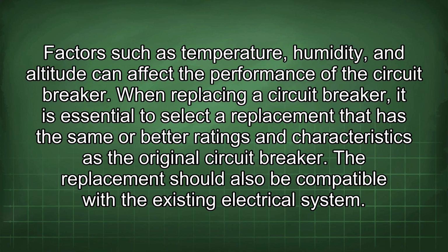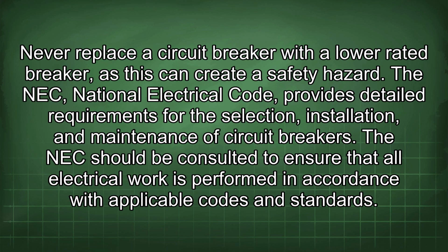When replacing a circuit breaker, it is essential to select a replacement that has the same or better ratings and characteristics as the original circuit breaker. The replacement should also be compatible with the existing electrical system. Never replace a circuit breaker with a low-rated breaker, as this can create a safety hazard.